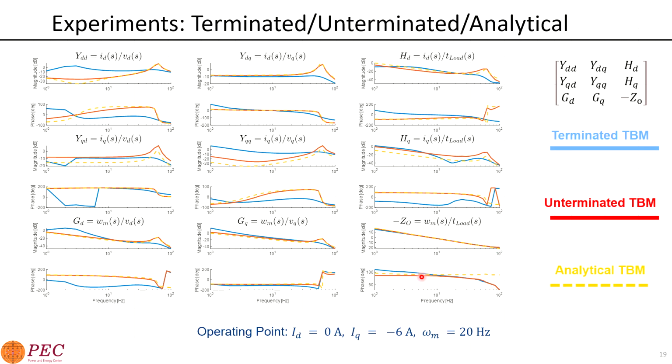And this is the experimental result. Different from the simulation results, here the red line relatively matches the dashed line, not that perfectly, but I think it is good enough. And we could see that at relatively higher frequency, when the frequency is closer to 100 Hz, the phase lagging or phase deviation is higher, or the performance is worse.